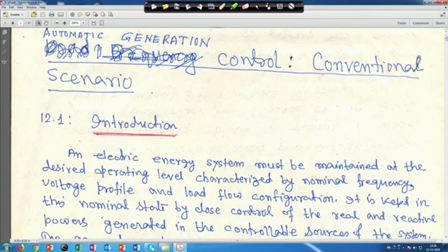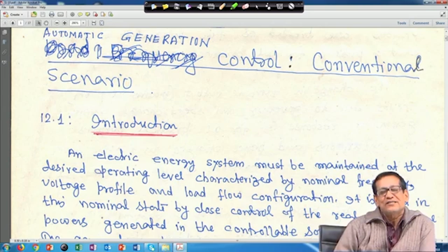In a power system, loads are changing continuously, because many loads are getting switched on or off continuously, and that is why a continuous disturbance will be there, right. But when this disturbance is very small compared to a large load, a small change in real power affects the system frequency, but leaves the bus voltage magnitude almost unaffected.